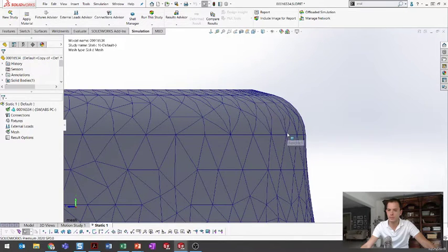Look at this one here, right? I got that mid-side node right in there. Instead of one line going from point to point, I have an extra node added in there, and that allows it to map to this geometry really well.